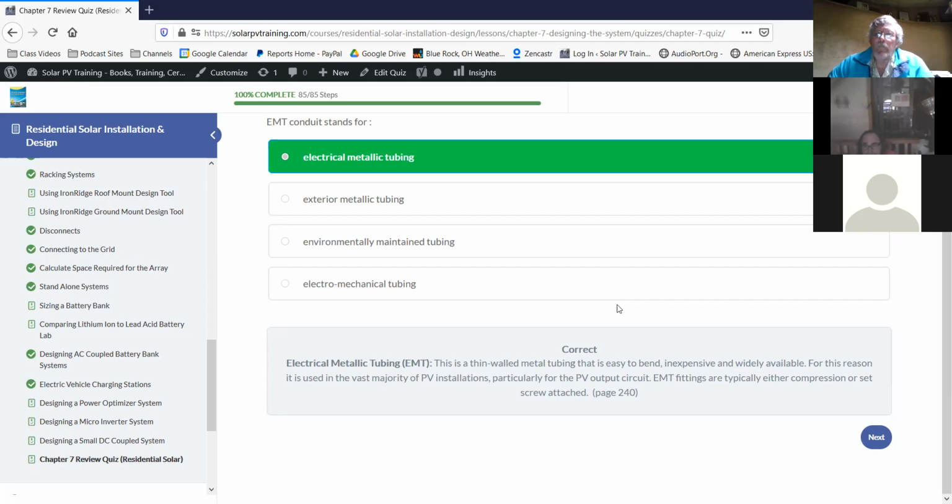Okay, and also when we get into the labeling portion, it is also required that every 10 feet on your metal conduit, it must be labeled as photovoltaic circuit, and within 1 foot of every bend and wall penetration. So they seem very, very keen on you making sure everybody knows that's a PV circuit. So you might be right, but I still don't see the logic to it myself. But, you know, who am I to question? They never asked my opinion, so I guess I won't give it.